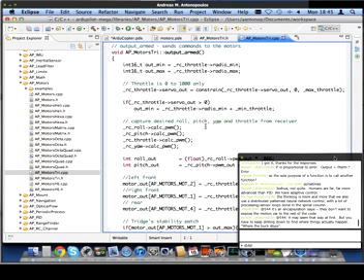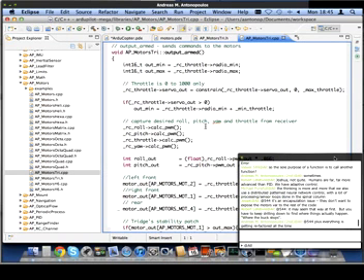So now in this function, the GRC1, GRC2 that we talked about before have been renamed essentially into RC roll and RC pitch. But these are the same objects. The RC roll is just a pointer to those global objects. So what we do here is you can see we need to first of all make sure the throttle is a reasonable number, not too big, not too small.